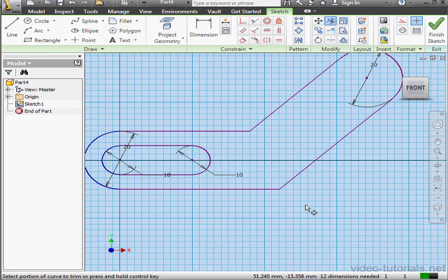However, applying dimensions and constraints to your sketch is a good practice. And basically, it'll save you a lot of hassle later on. Let's say, for example, you accidentally move some geometry while you're sketching, and then later on in your project you find a problem and you need to do a forensic deconstruction. If your model is pretty complex, that can be really time-consuming. If only you had applied some dimensions and constraints while you were sketching, you'd have saved all that time.